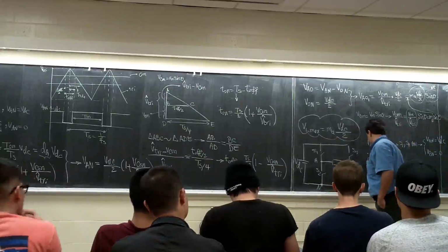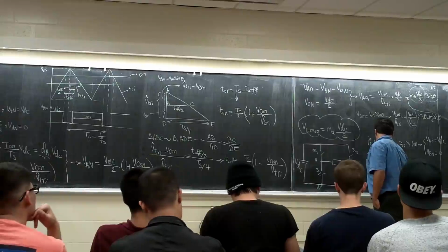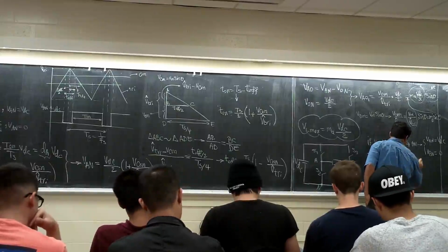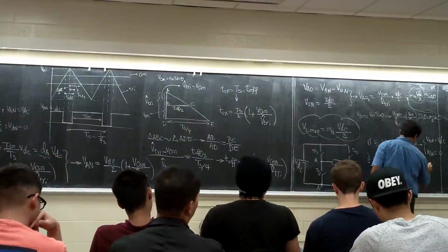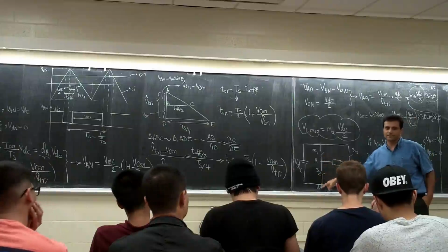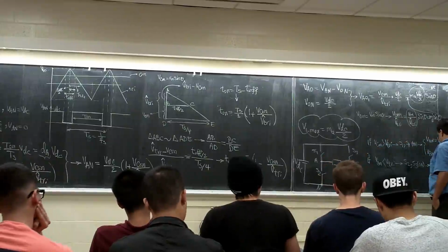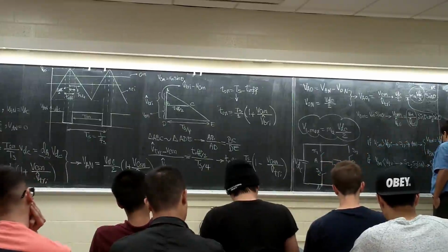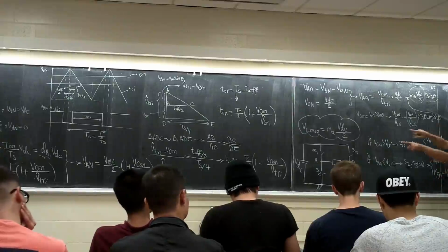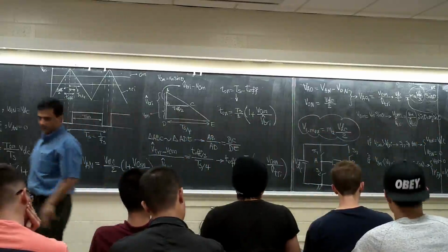Now another case is if V control is less than VTRI. Basically S2 and S3 are going to be on. So let's see what's going to happen. If S2 is on, how much is the VAN? 0. How much is the VBN? VDC. Basically, look at here, VAN, these two cases are exactly what we had over there, right? What we went through. Nothing changed about VAN.